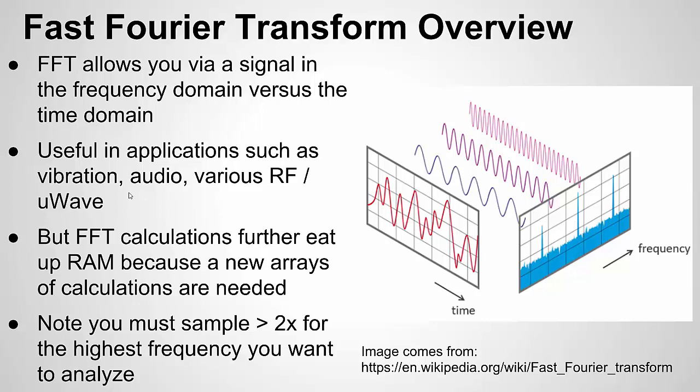If I see noise content at that exact frequency that the switching power supply is switching at, I know it's my switching power supply contributing too much noise to my signal.